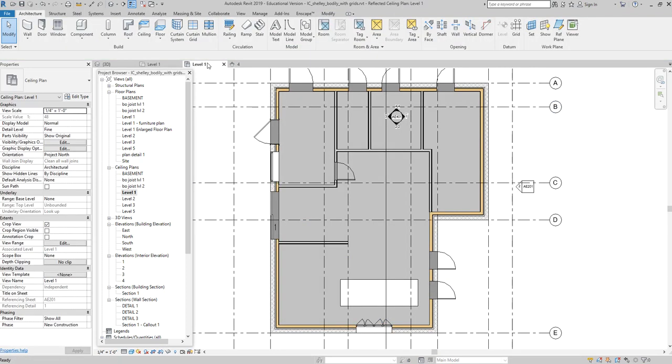We take a different approach with ceilings. While we don't want to attach the ceiling to the bottom of the floor above, the floor above usually acts as some type of structure for the ceiling, whether you're screwing drywall to joists or, like in this case, hanging the ceiling off the deck above.